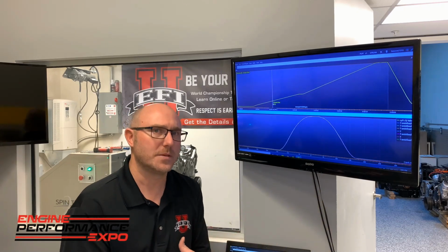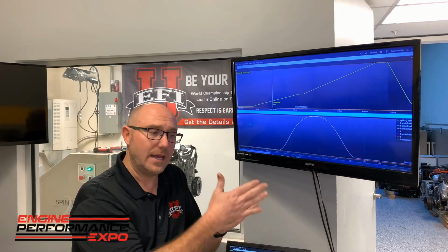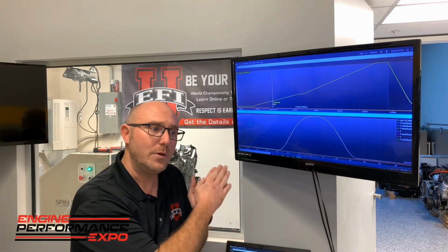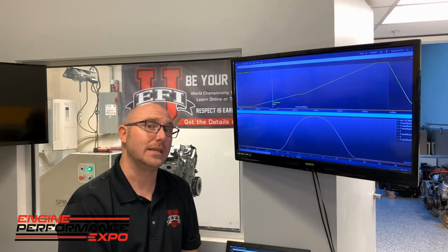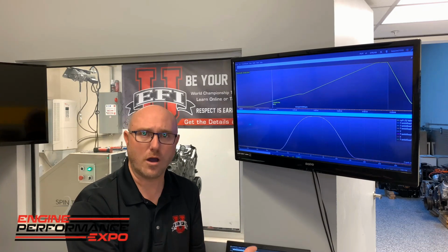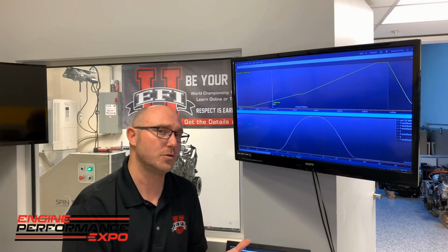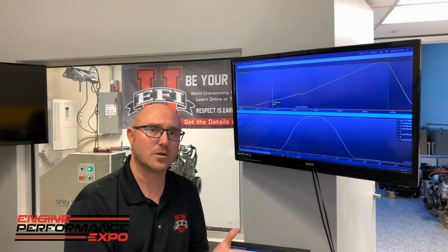The Spintron's the opposite. We have a big electric motor in the Spintron connected to our engine assembly, and we can then use the electric motor to spin the engine. That way we don't have the combustion process taking place. We don't need the water, things like that. It's mostly a complete engine. We typically don't have the actual crankshaft or the pistons or connecting rods.